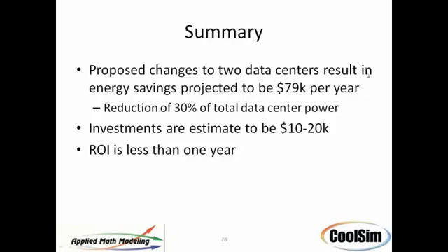All right, our last question is, with return air temperature control, can raising the return air temperature work if you can't control supply temperature? Well, yes, because if you slow down the flow rates, if you can slow the fans down on your crack units, the return air temps are going to be higher. So remember the relationship is that heat transferred is mass flow rate times density times delta T. So you can hold supply temperature constant, reduce the mass flow rate, and your return temp is going to go up.